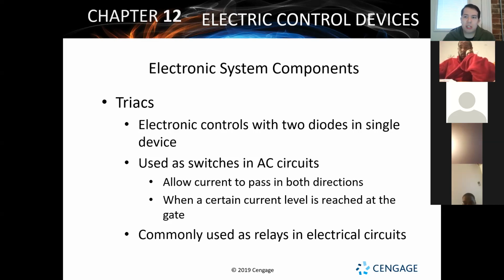That's one of the biggest mistakes guys will make: people will rush to the conclusion, well, I've checked my contactor, I've checked my transformer, I've checked this, I've checked that, and they all seem to be working, but I'm just going to say it's the control board because that's an easy solution. I don't have to check any more components. I'm just going to swap out the control board and see if it runs. I know guys that have done that for their troubleshooting. If it doesn't work, then it's something else.